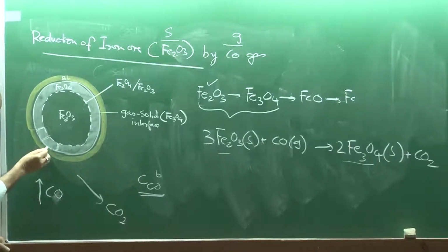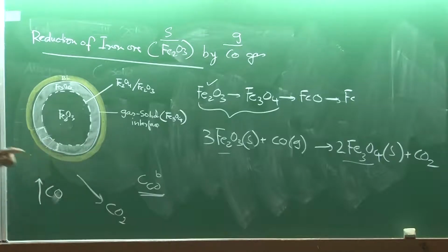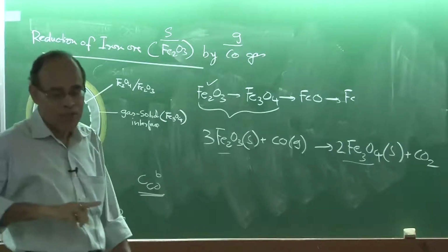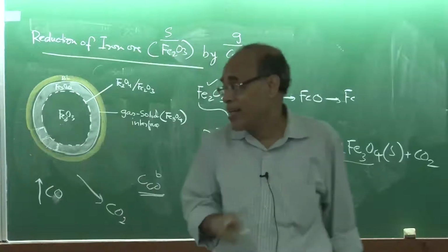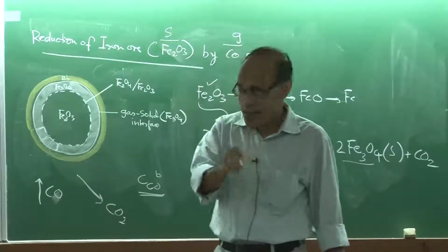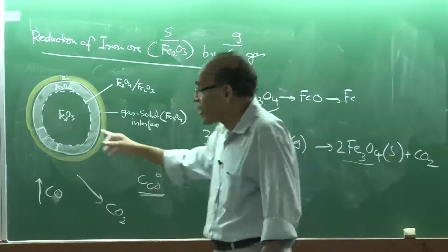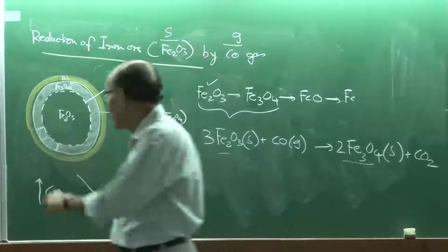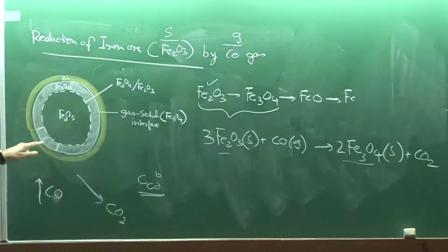Alternatively, carbon monoxide from here can transport through the bulk also. So there is a parallel transport, and this we have studied, okay? I have said that we can apply it in the context of grain boundary as well as lattice diffusion. So that concept can be applied, and here the diffusion could be represented by an effective diffusion coefficient. Okay?